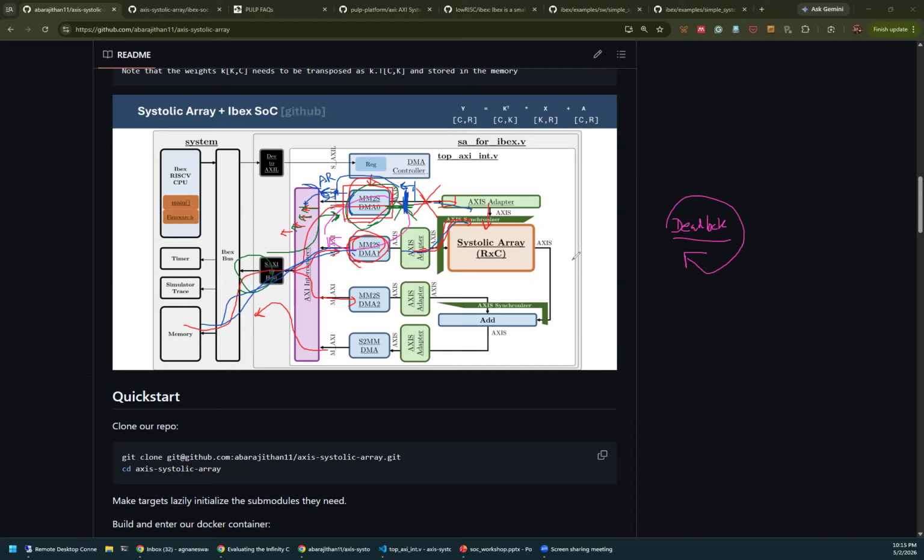And the other one is that I wanted to experiment with the crossbar and see how it works, whether it has any problems. Can I add new modules into that? Because I have not used the open source crossbar, I've used the ZYNQ crossbar all this time. So I was thinking I want to see how that works. And the crossbar is a little more complicated module than the interconnect, so that's why I used it. But in your case, if you don't want concurrent read and write, then you can use the AXI interconnect as well. Okay, that's a good question.